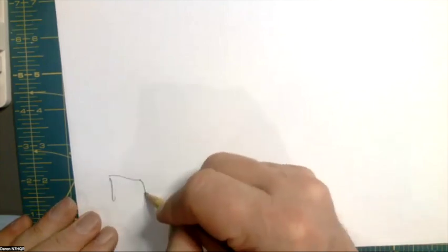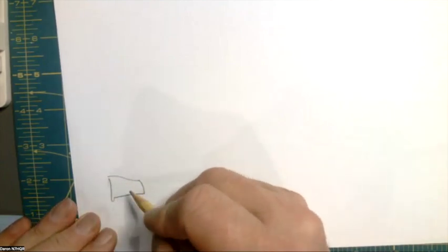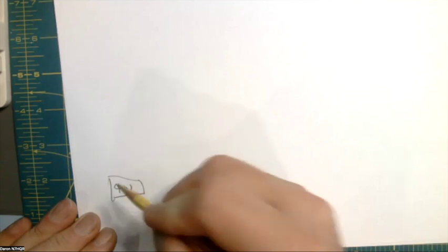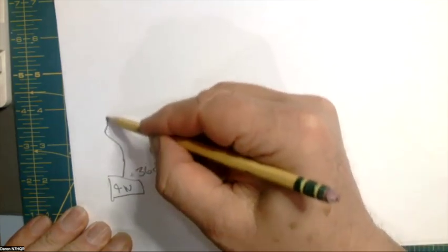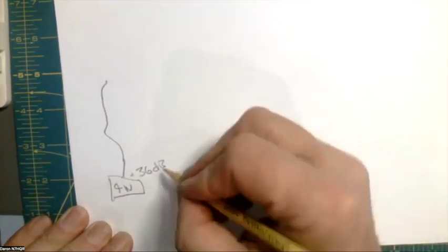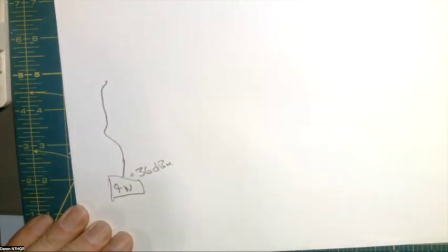Okay, so let's look a little bit at the basic, if we were to put it into something that we might use. I'll do my very technical illustrations here, almost left-handed. Here's our 4-watt little radio that we're going to use. So we know that that is 36 dBm that we're starting with.